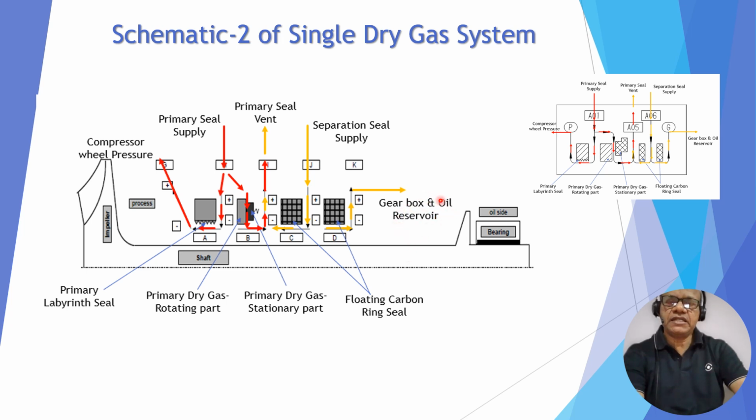Normally the oil reservoir is in a vacuumized state, that is, the pressure in the oil reservoir is less than atmosphere. So the same thing is shown in another schematic for better understanding of the single dry gas seal system.